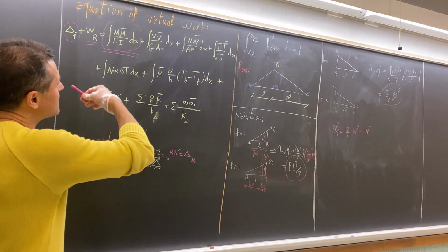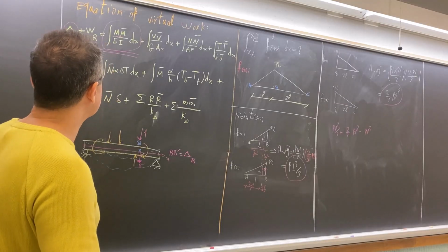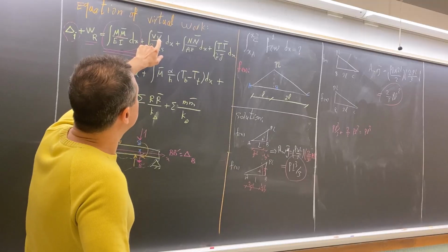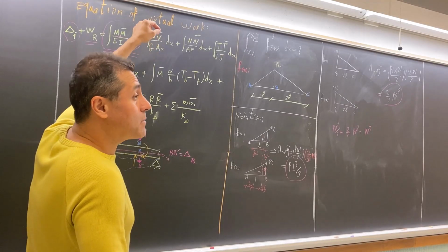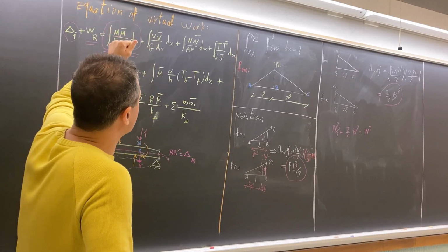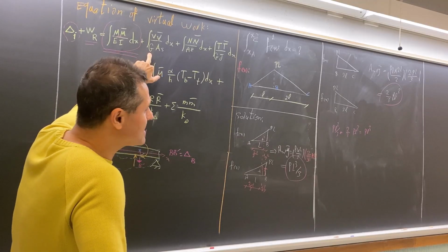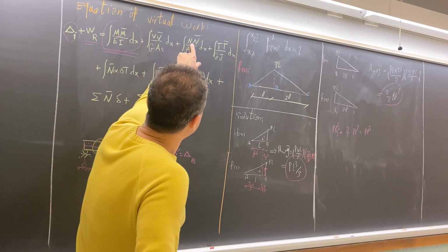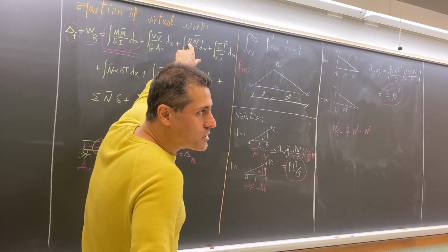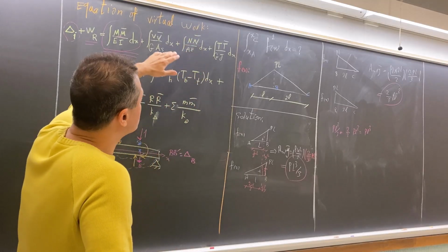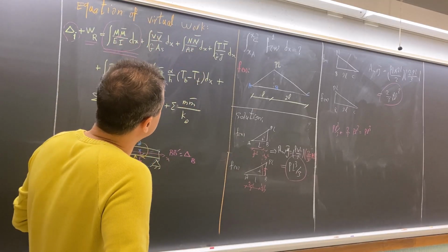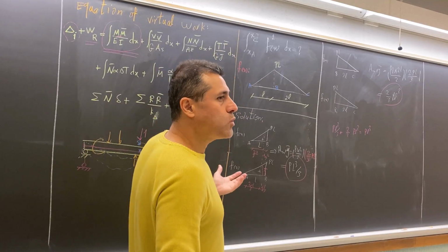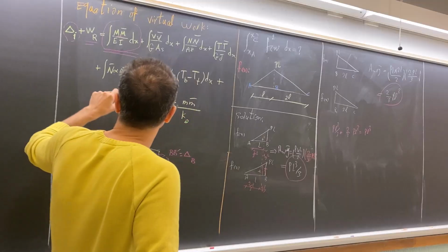So now to just introduce these parameters, because Reis was asking, V is the equation of the shear force, V bar is the equation of shear force when you apply a unit virtual load. G is the shear modulus of elasticity, AS is the effective area, N is normal force, N bar is the equation for normal force when you apply a unit virtual load, etc. T is torsional moment, so you know T bar is the same torsional moment when you apply unit load.